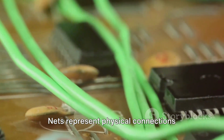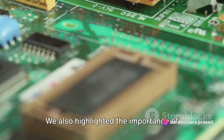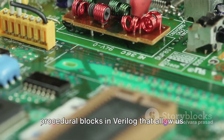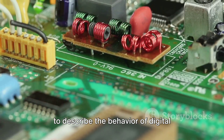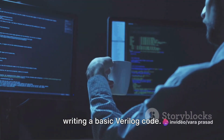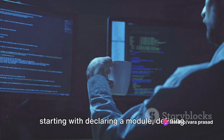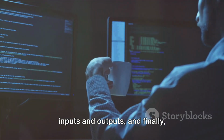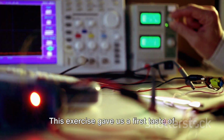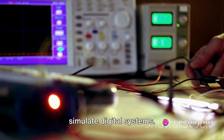We also talked about the different types of data in Verilog HDL, including nets and registers. Nets represent physical connections between hardware, while registers represent storage elements. We also highlighted the importance of always and initial blocks, which are procedural blocks in Verilog that allow us to describe the behavior of digital systems over time. Then, we took our first steps into writing a basic Verilog code. We used a simple AND gate as an example, starting with declaring a module, defining inputs and outputs, and finally, describing the behavior of the gate. This exercise gave us a first taste of how Verilog HDL can be used to design and simulate digital systems.